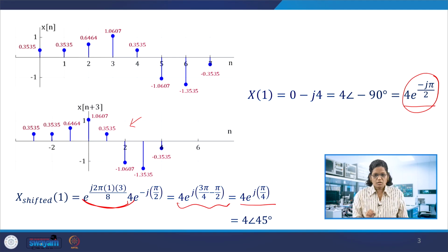Moreover, in the DFT, we compute all the bin indexes with k varying from 0 to N minus 1. Suppose I want to know only about the fundamental, what is the magnitude and phase of this fundamental in this particular signal. If I do a DFT, then DFT computes all the kth bins. So instead of that, can I use it without varying k from 0 to N minus 1? I'm interested in only one particular harmonic or fundamental in the signal. So k equal to 1, or k is 2 alone, second harmonic, third harmonic, fourth harmonic, and so on.